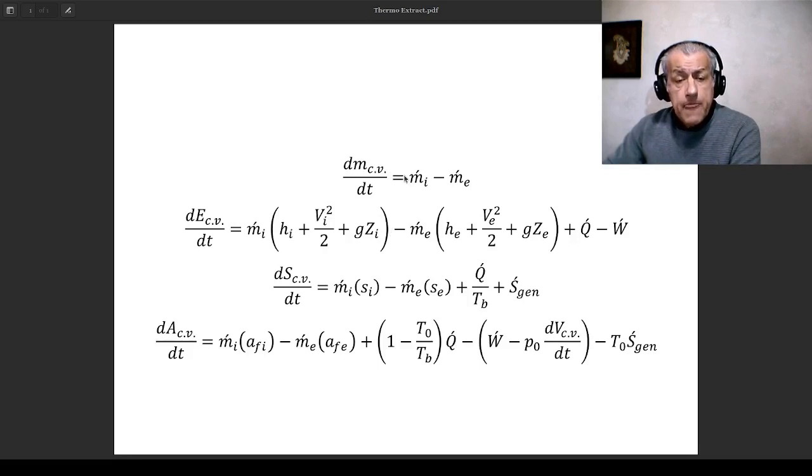We could, in fact, we shall use mass conservation for both components independently, but the enthalpy of the mixture is also possible to calculate. And so what we would need in our calculations are two equations for mass conservation and a single equation for energy equation.